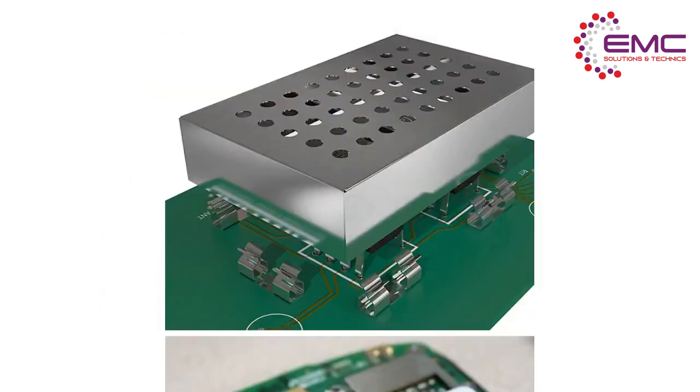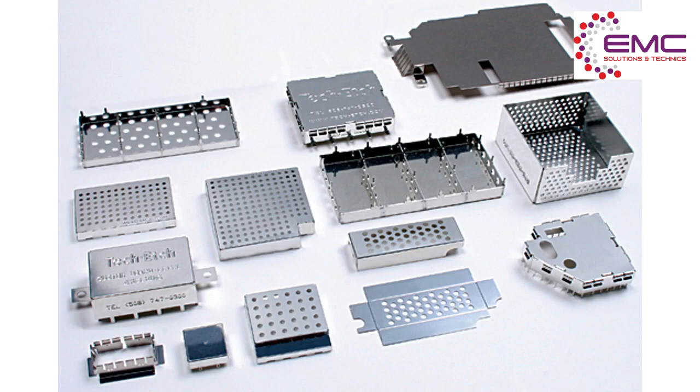Shielding. Shielding is not an electrical solution but a mechanical approach to reducing vulnerability to electromagnetic interference. Metallic packages, that is conductive or magnetic materials, are used to prevent EMI from escaping the system. A shield may be used either to cover the whole system or a part of it, depending upon the requirements.